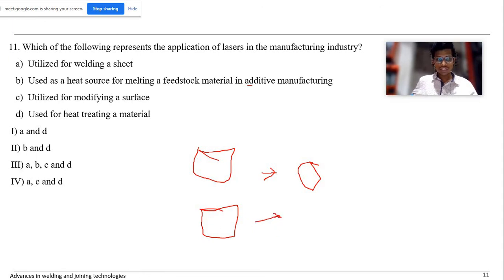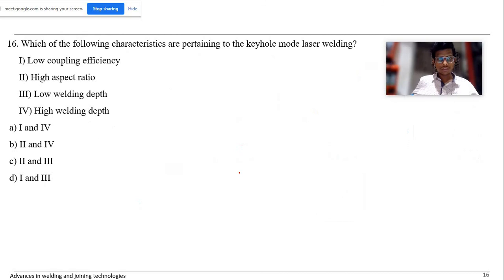If you want to deposit this kind of block in additive manufacturing, what you will do is first generate the CAD model in some software, then generate the tool path. With the help of a heat source and filler metal, according to the CAD model and slice information, I will deposit the component layer by layer to get this kind of block. Sorry for my poor drawing skills. Next time I will try to use a pen and touchpad. Then it will be better. So that is additive manufacturing.